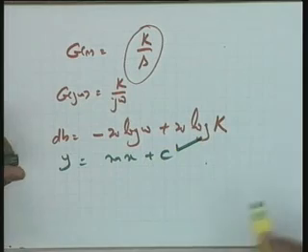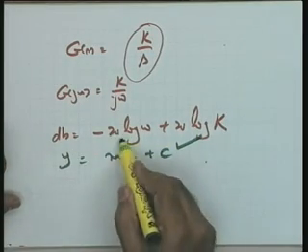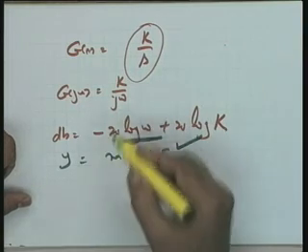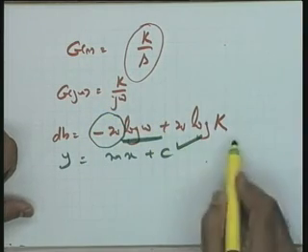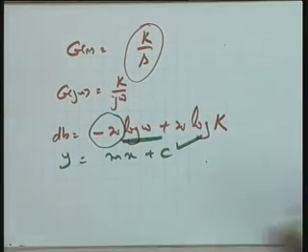The only thing is that now the constant has changed. In your standard straight line equation, with log omega equal to x, it is log y equal to mx plus c. So it is again minus 20 dBs per decade. The only thing is that the point from which this line is to pass is shifted. So it is better to plot it directly this way instead of adding the two plots.